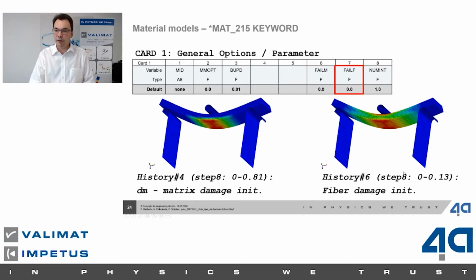On the other side, if we are looking at the failure of the fiber itself, as we're using a micromechanical approach, we now know what stress is coming into the fiber. We know we are at about 10%, 30% of the fiber strength, so quite far away. So it's quite clear in that case, first the matrix will fail on the tension side, and the fiber will then be pulled out during that. Not the fiber will fail first. So that's some results that we directly see out of the simulation, which you won't see in a composite build-up.